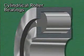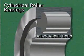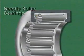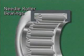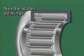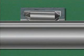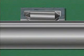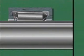Cylindrical roller bearings have rollers that are shaped like cylinders. These bearings are designed primarily to support heavy radial loads. Needle roller bearings are similar to cylindrical bearings, but the rollers are much thinner. Needle roller bearings can support a great deal of radial load because many of the thin rollers can be put into a bearing. Needle roller bearings are often mounted without an inner ring or a retainer. Instead, the rollers ride directly on the surface of the shaft. Because these bearings can be mounted without an inner ring, they are often mounted on shafts where space is limited.